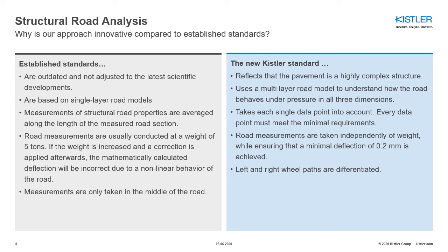Road measurements are usually conducted at the weight of 5 tons. If the weight is increased and a correction is applied afterwards, the mathematically calculated deflection will be incorrect due to a non-linear behavior of the road.